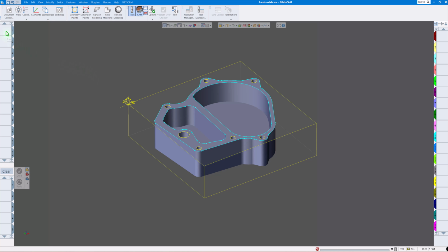So basically, to do that, you can click anywhere in this list and just right click and go to Load Tools. Notice there's a Browse and a Set Folder. You can actually create a folder and set it to that folder. So you can create a folder for, say, all turning tools, all milling tools, or a particular tool list. If you have a horizontal, which some horizontals have a hive, and you could have 300 plus tools on there, you could just click on Set Folder and click on that particular machine, and it'll load all the tools up in your machine.